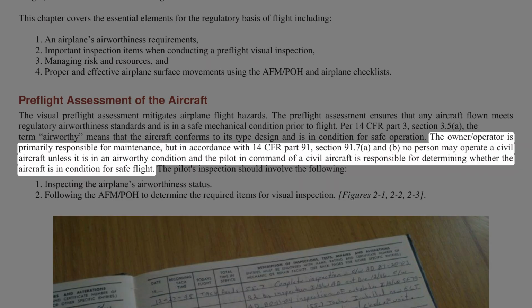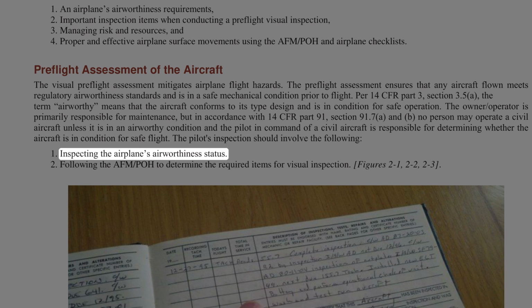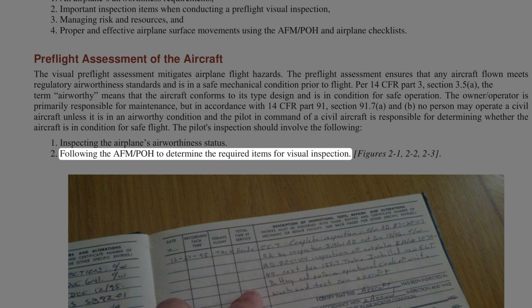The owner-operator is primarily responsible for maintenance, but in accordance with 14 CFR Part 91, Section 91.7(a) and (b), no person may operate a civil aircraft unless it is in an airworthy condition, and the pilot in command of a civil aircraft is responsible for determining whether the aircraft is in condition for safe flight. The pilot's inspection should involve the following: inspecting the airplane's airworthiness status, following the AFM, POH to determine the required